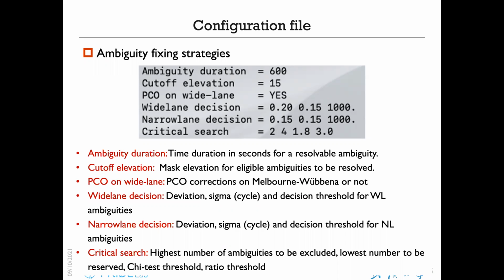So you need to be alerted here if you wanted to change these quantities, these values here. Normally, you don't need to change them. You must have very professional knowledge of GNSS before you can make any decision on these quantities. Normally, 2 and 4 will be enough, because in some cases, you have very bad data quality.